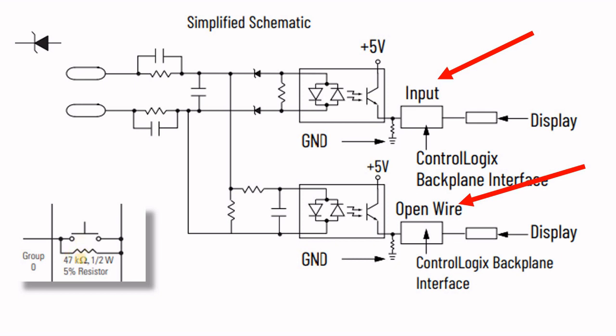The reason is, if you look at it from a different perspective, your limit switch is completely open or completely closed. So if you have a broken wire, you will never be able to recognize you have an open wire until you push the limit switch or the push button, and at the same time notice that your PLC cannot recognize the change of your channel.